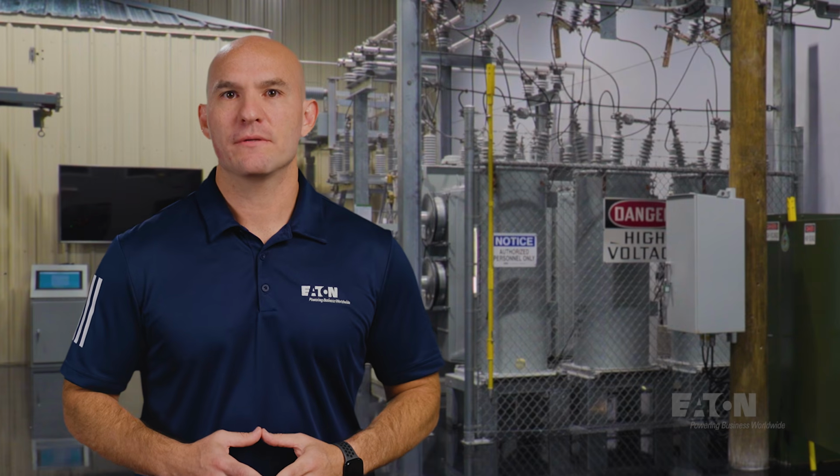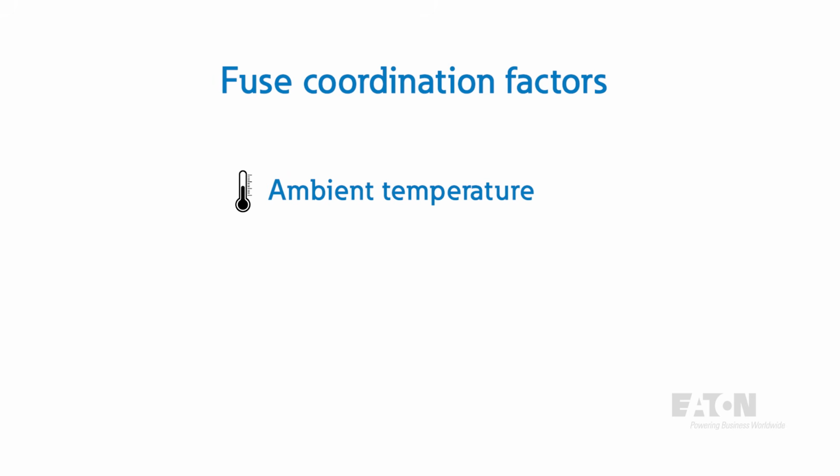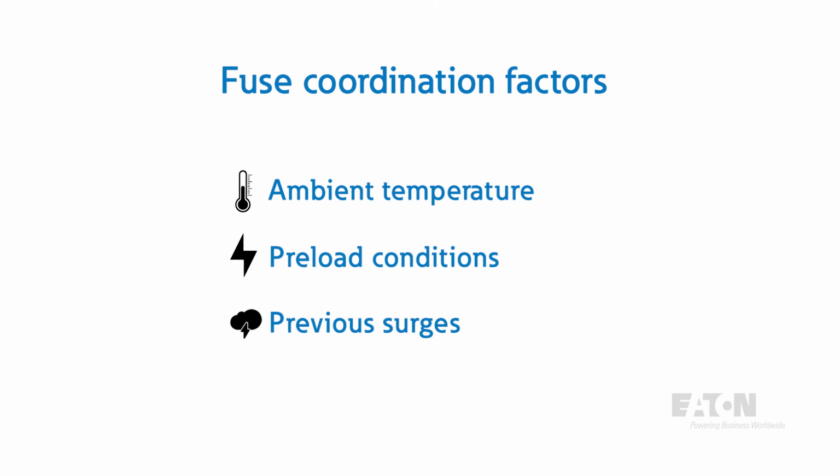These are ideal for high fault current areas or sensitive loads like hospitals and industrial plants. Fuse coordination isn't just about current. It also depends on ambient temperature, preload conditions, and pre-damage from previous surges.